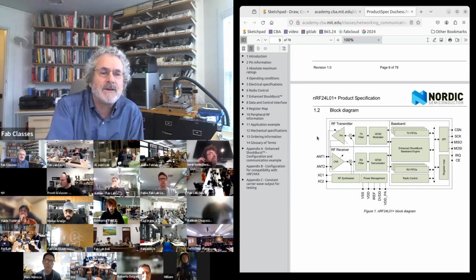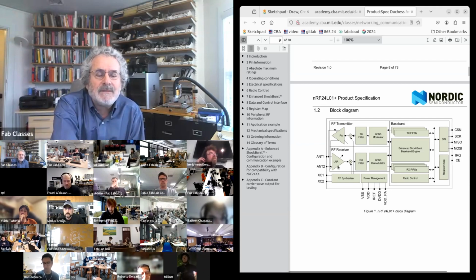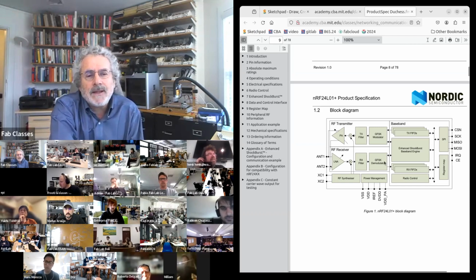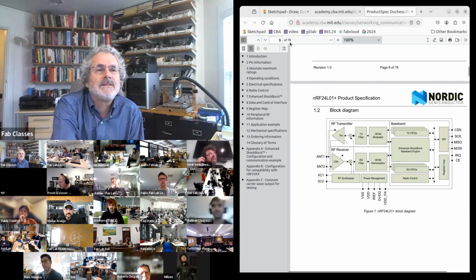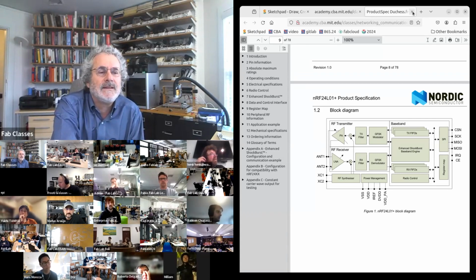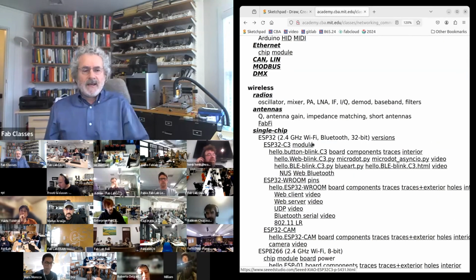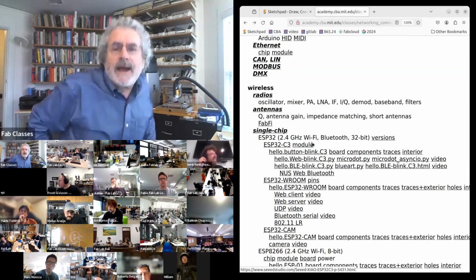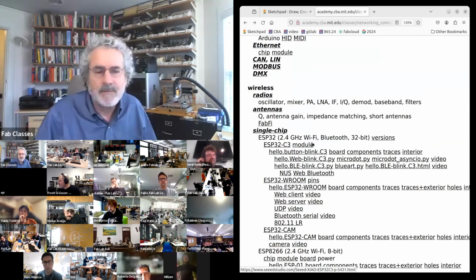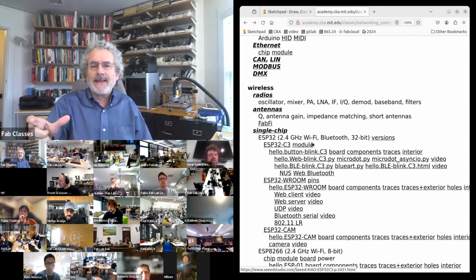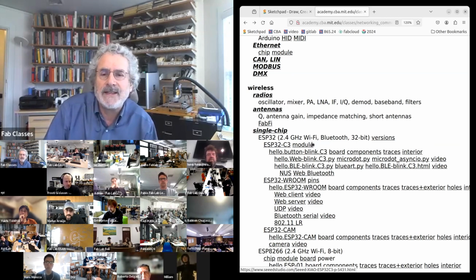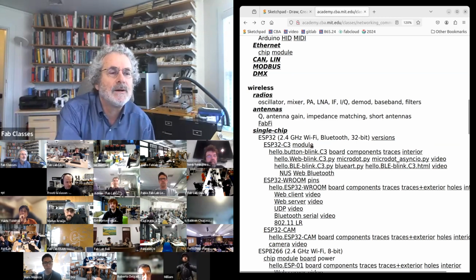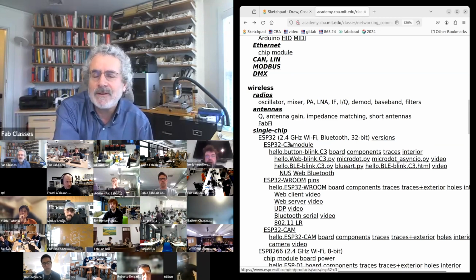But what's coming back is a very low-level signal. So you need to separate the big signal from the little signal. Then you need to pull out your data, and then out comes the message. And so all of that's running in these single chip radios. Once upon a time, we used to use those from scratch, and we would build everything. Now you can get, thanks to really our friends in Shenzhen, these more complex chips that have the radio plus the protocol.